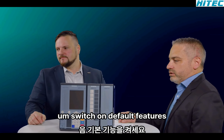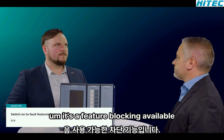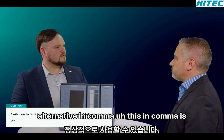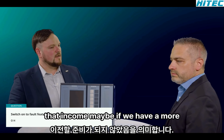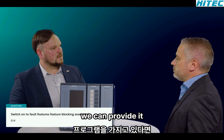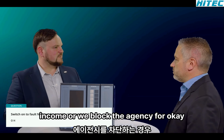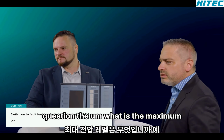Switch onto fault features. Is a blocking feature available? Yes, a blocking feature is available. Normally, if you have a fault on the alternative incomer, this incomer is blocked. That means the HSBT function is not ready to transfer to that incomer. Maybe if we have a more complicated application, then we can provide that this application will transfer to another incomer. But normally, if there is a fault on the alternative incomer, we block the HSBT function. Okay, good.